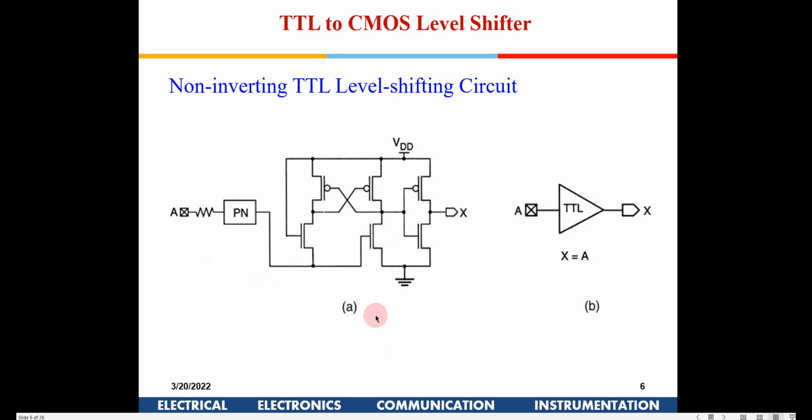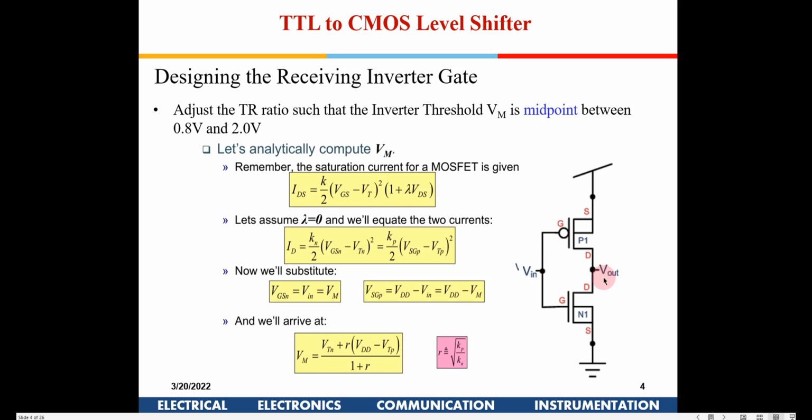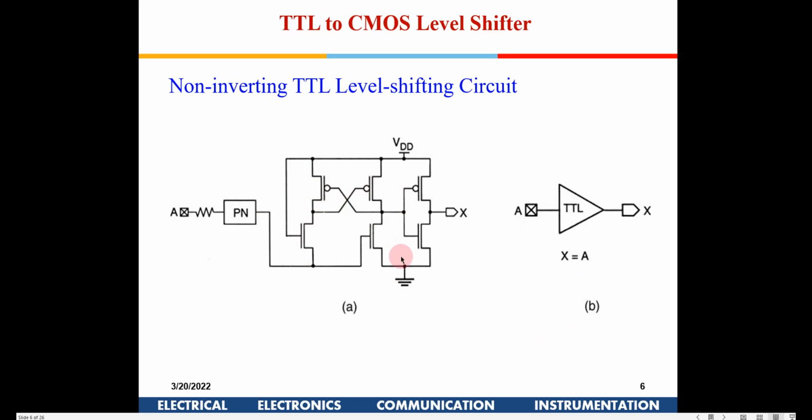Okay, so now this is another level shifter. In this particular case, the sign of the signal changes, it gets inverted, because we are using an inverter here. If you don't want that to happen, then you can use this kind of circuit also. So you have an input out here, and this is the inverter. But this inverter is cross coupled with one more inverter out here. Whenever the input signal is going high, this output voltage will become 0 here, right? If it becomes 0 here, this PMOS will be turned on, and that will in turn turn off this one. So faster switching is possible, and again you are using one more inverter, so that here you have an A bar, and as X you will get back A here, right?